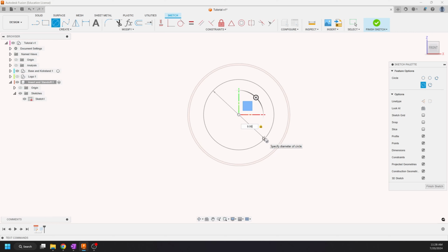Those acrylic rods, they have some deviation with the manufacturing. So it could be anywhere from 10 thousandths to 20 thousandths low. So if you make this smaller, it's going to grab onto whatever size that you put in. You may have to mess with this a bit, but due to the flexibility of the TPU, which is why I designed it in TPU, it's going to deform enough to capture that standoff.